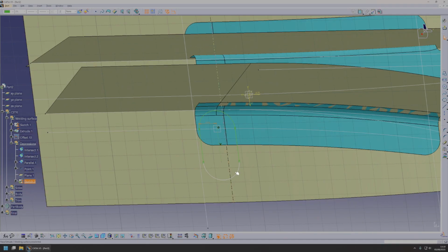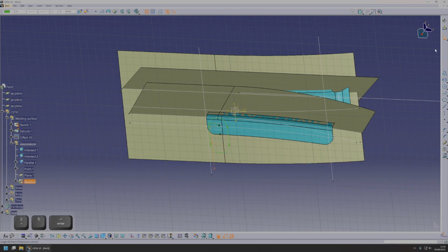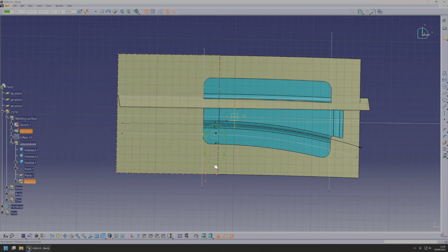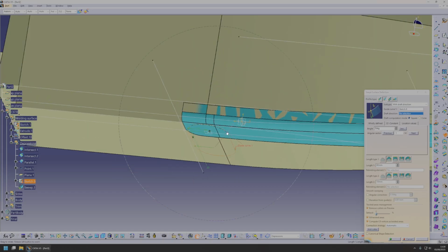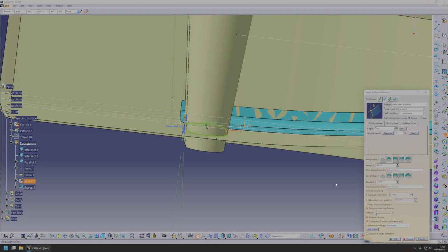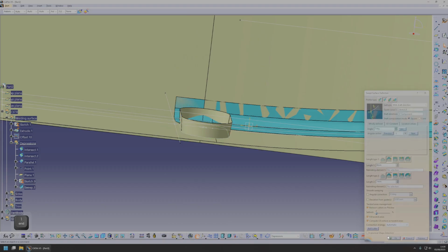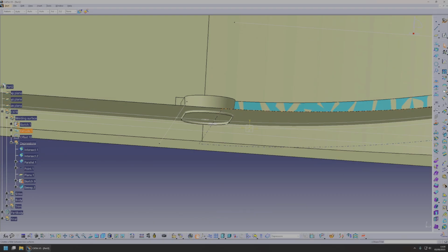This is actually the value that we might end up needing. And here we're gonna go with 25, I don't know, this doesn't matter. Just need to make sure it's past the flange of this part. Okay. This we're going to go with another sweep with draft direction. Go with set. This time is this surface. We don't need it that much, so we don't need to go all the way. This is fine. So this is the first point that we're gonna use.